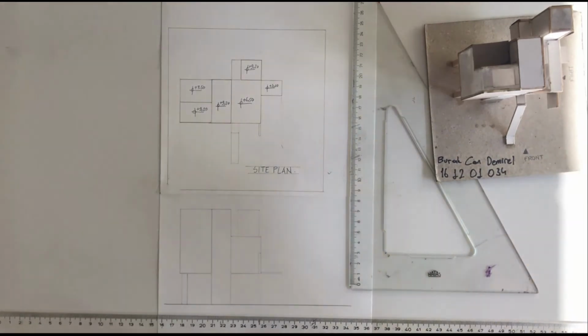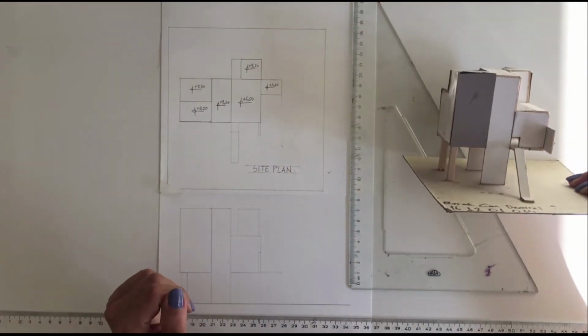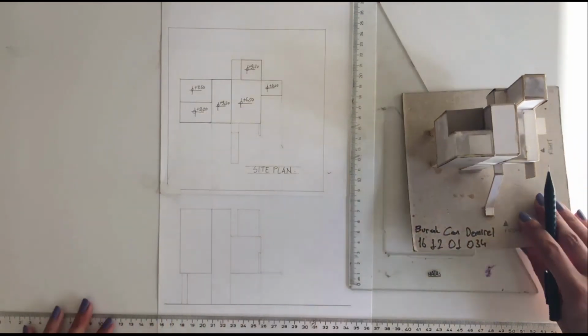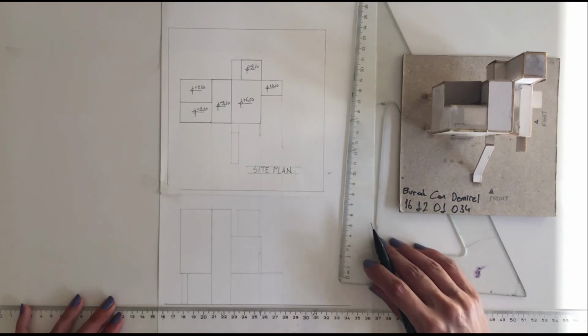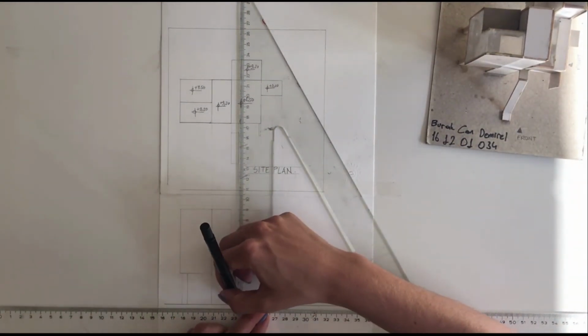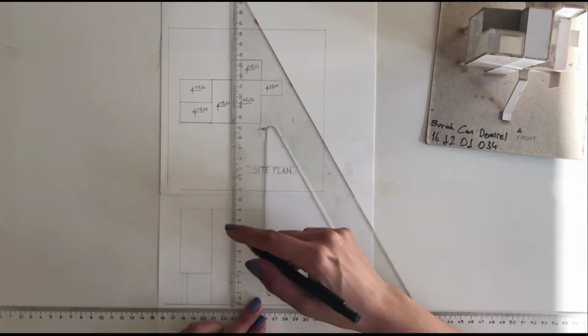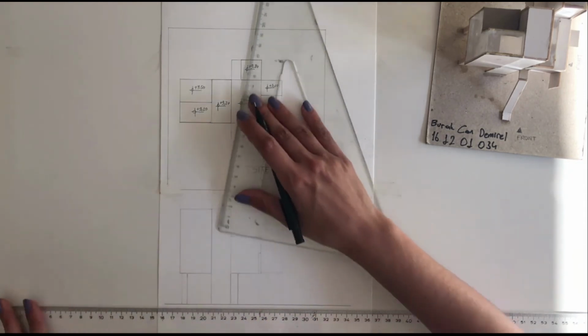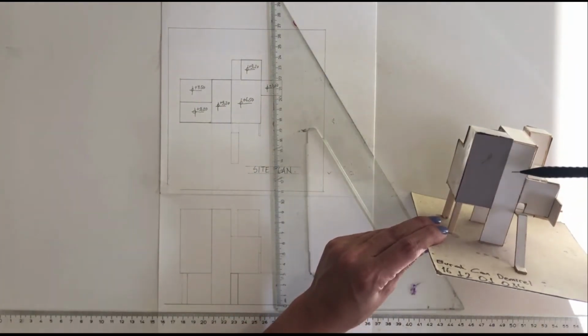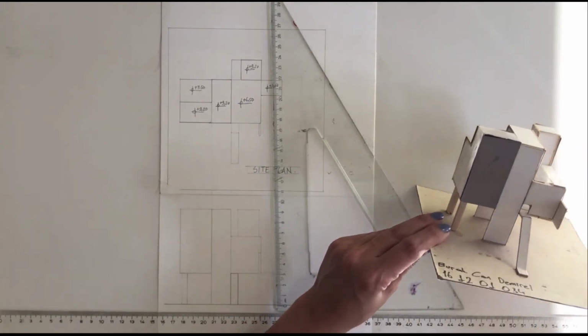I need again to make some lines heavier and darker than the other ones to make my drawing readable. This is the surface which is on the most front, so it's going to be the darkest one. It must be. So I'm going to draw it with a heavy hand with heavy and dark lines. These 3 surfaces are on the same level.